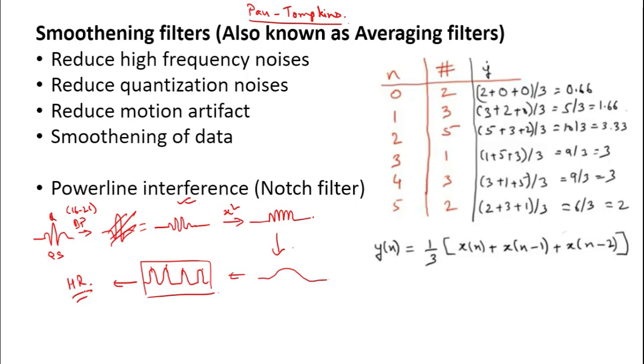So here see, we started with an ECG signal which we considered that there are no noises. Okay. But to get some meaningful result, we had to apply a smoothing filter over here. Okay. So after getting a typical type of the signal, then we went for the calculation of the heart rate.